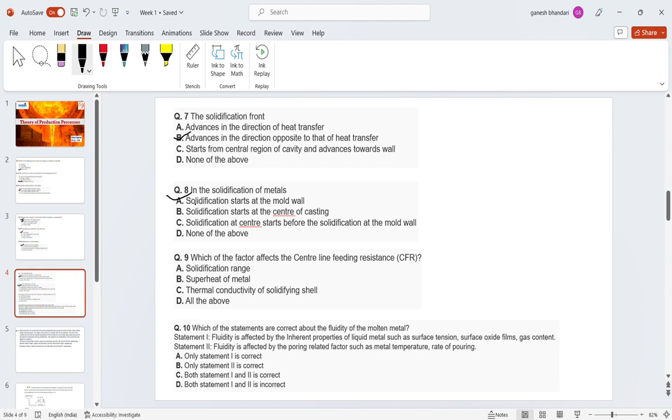And the relevant forces between the mold and the surface will also come into picture. Then the melting point, everything will come into picture. So then you will be writing the Navier-Stokes equation and solving those, doing simulation, and after that you can conclude whether the effect will be more due to the particular cavity or due to the solidification of the metal.